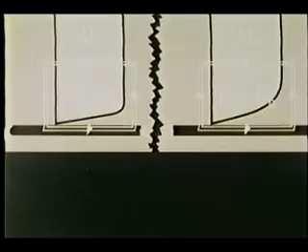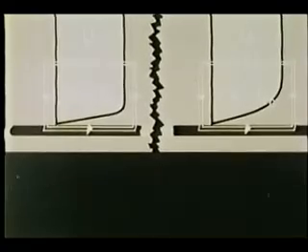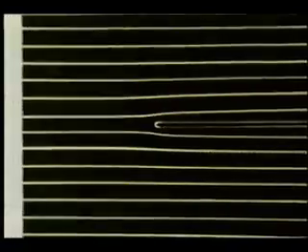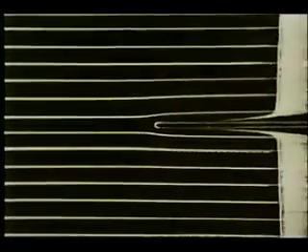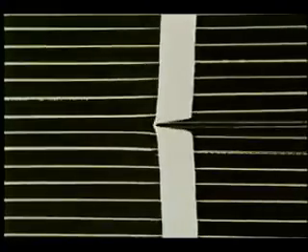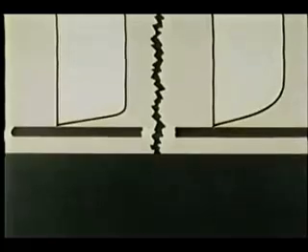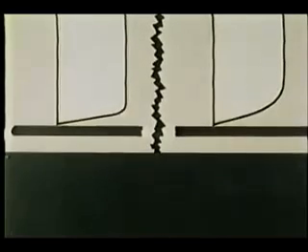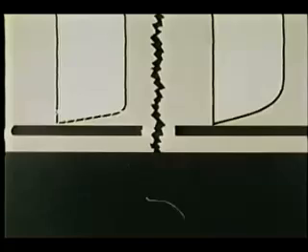The total amount of vorticity within each contour is the same. Because there is no vorticity upstream of the plate, and because the circulation per unit length along it is constant, we conclude that all of the vorticity is generated in its length. Upstream, 95% of the total vorticity is contained within this area. Downstream, 95% of the total vorticity is contained within this area.